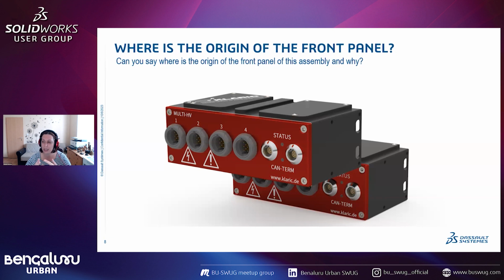In this case we're using Co-Designer, so I'm working directly in SolidWorks and positioning the connectors for the electronic boards. But in other cases, you must give coordinates to the electronic engineering department, and they will know where to place the connectors. And the only way to ensure that everything is correct when you don't have this collaboration between the software is if you define one origin for everything.